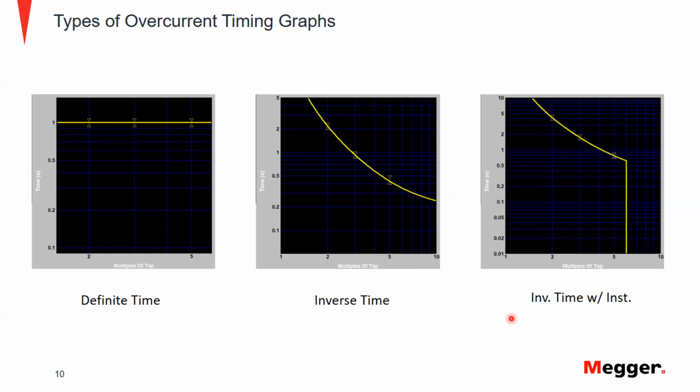The instantaneous element that's tied into the inverse time characteristic as well is very effective in reducing operate times of severe faults. They don't offer any selectivity because they have different characteristics, and they're instantaneous for a reason: we want to get the fault current off the device in the yard as quickly as possible to minimize damage.